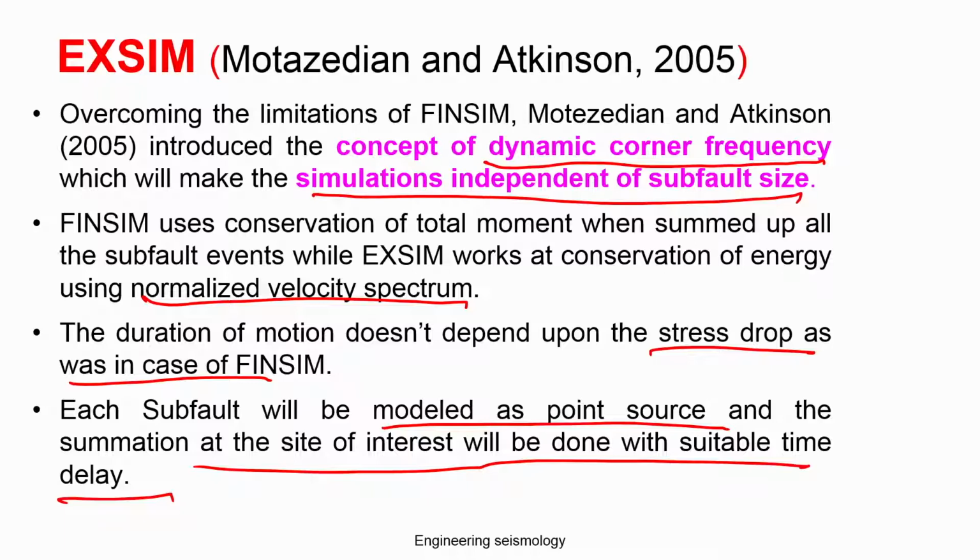As of now, the SMSIM models are the better ones. Below magnitude 7, EXSIM and SMSIM do not make much difference. For earthquakes above 7, you need to use EXSIM, depending upon the place. If you want to use simulation in peninsular India, where you expect a moderate earthquake, below magnitude 7.5 or 8, you can go for SMSIM. Magnitudes 6, 6.5 and so on you can easily create with the SMSIM model.